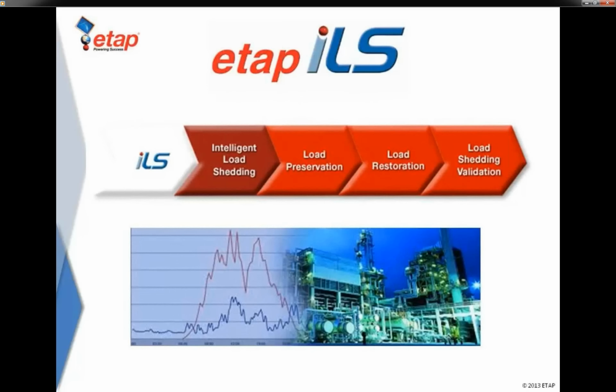Load shedding calculates the minimum required megawatt to be shed for each subsystem according to its type and location of the disturbance, or the actual operating generation, spinning reserve, the loading configuration, and load distribution and priority. Again, being a model-based solution, ETAP-ILS has all this information, and it can then be used to optimally configure the triggers and the commands to trip the loads in an optimum fashion.